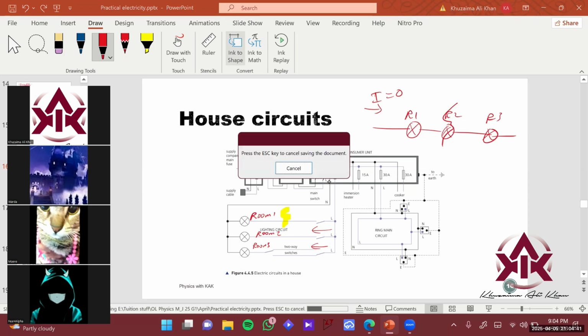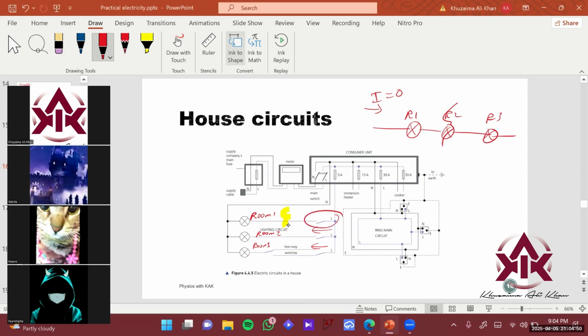And it's also easy to basically find out the issue, right? If you know okay, room one is not lighting up, you have only an issue over here, right? So in series, you won't know okay whether you have an issue in room one or room two or room three. So your electrician will have to check every part of your room, right? So this is basically how you lay out the connections of electrical supply in your house.